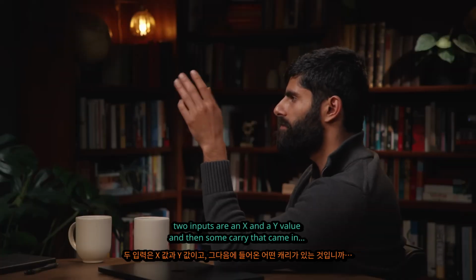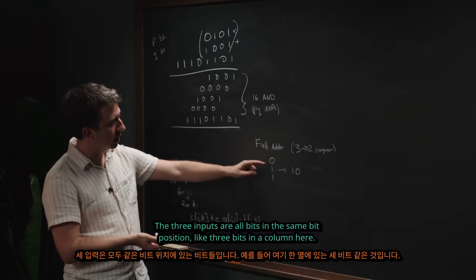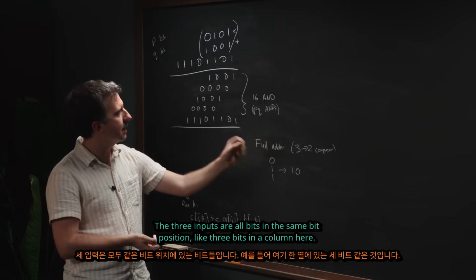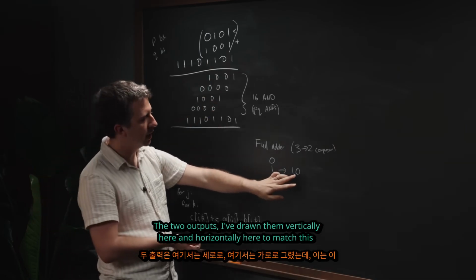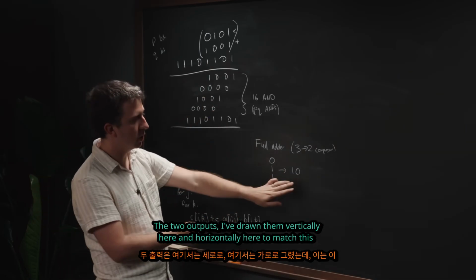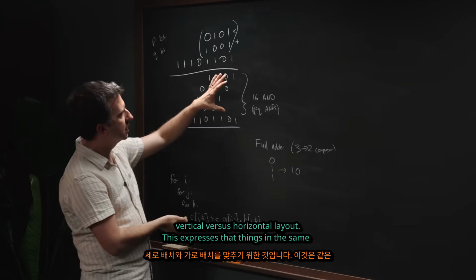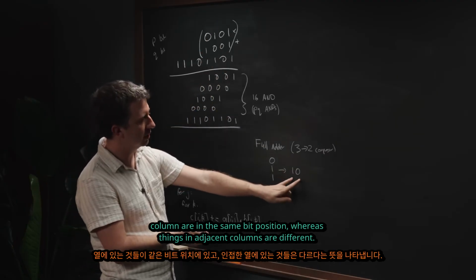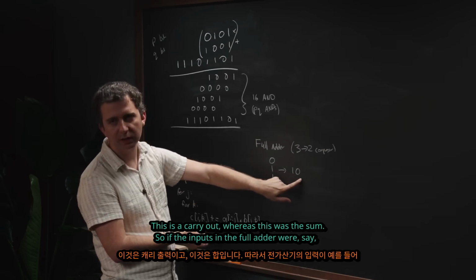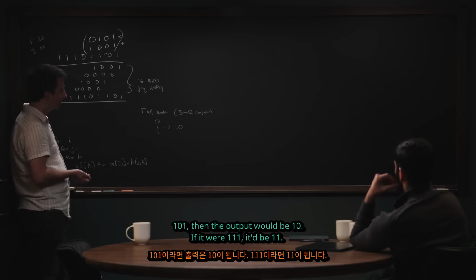The 3 inputs are an X and a Y value, and then some carry that came in. The inputs are all bits that are in the same bit position, like 3 bits that are in a column here. And then the 2 outputs, I have drawn them vertically here and horizontally here to match this vertical versus horizontal layout, which is expressing that things that are in the same column are in the same bit position, whereas things in adjacent columns, this is a carry out, whereas this was the sum.